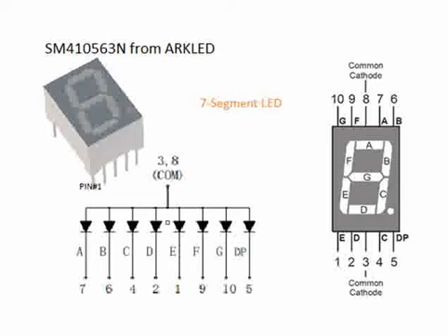So we will talk a little about the 7-segment display before going to Arduino Uno. This is how the 7-segment display looks. There are basically 7 segments, which is why it's named so. You can see this is 1 segment, 2, 3, 4, 5, 6 and 7. The symbol on the right is a representation in terms of alphabets for each segment: A, B, C, D, E, F, G. This is how we identify the 7-segment display.